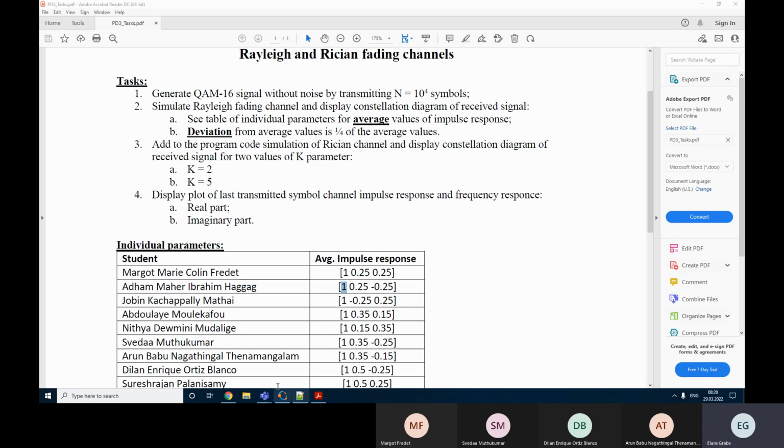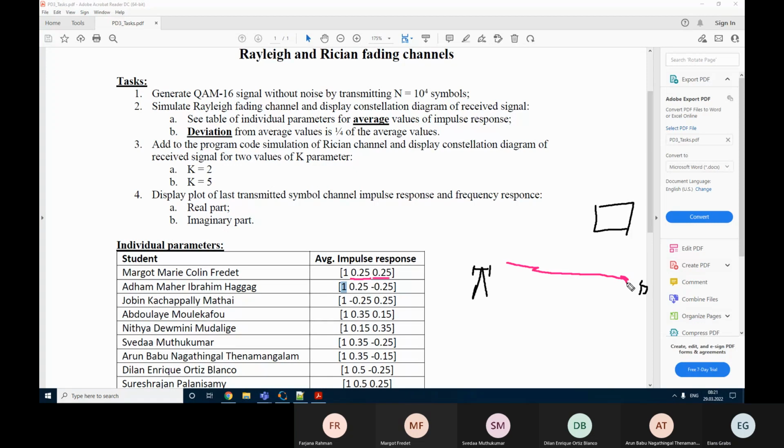Anyway, the other impulse response values, such as 0.25 and 0.25, are basically reflected signal coefficients. So basically, if we speak about transmitting from base station to mobile device, and we have direct line of sight signal with the value of 1, for example, and we have two objects reflecting our signal, each of them travels a longer distance with greater delay, and this delay is in fact affecting the position.